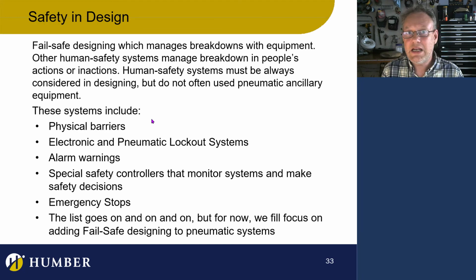But we design systems that will manage people not being safe and or machines that just break down. So we have to put that into mind. You have to put fail-safe design in for operators and for the machines, because everything breaks down. We can do that by putting physical barriers in. We can put electronic and pneumatic lockout systems, so if someone puts their hand in there, it just locks it down.